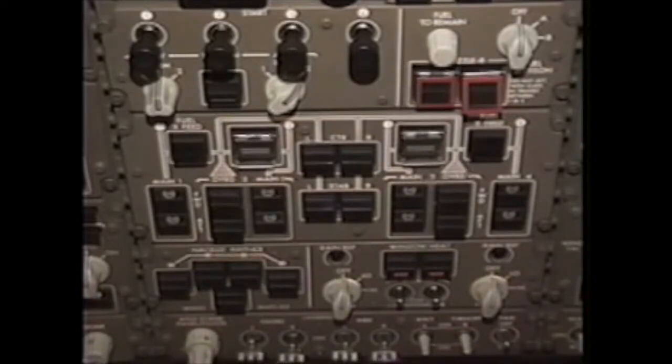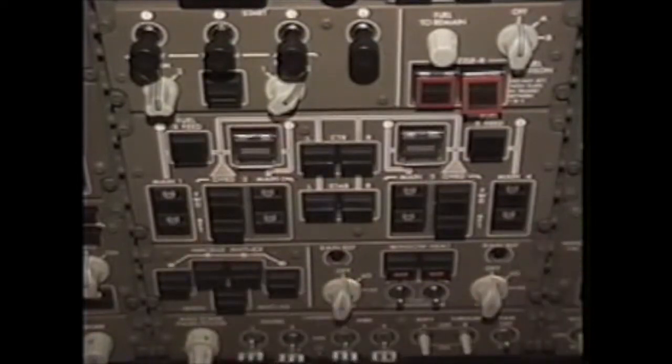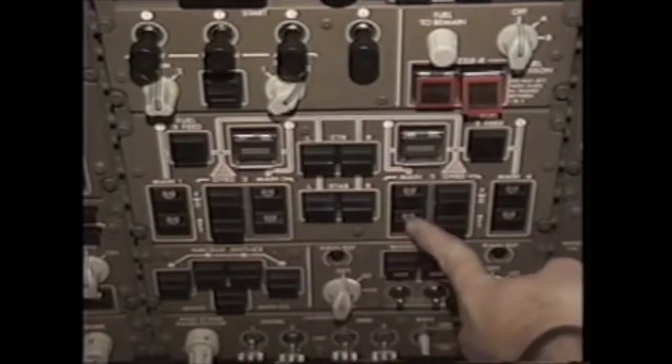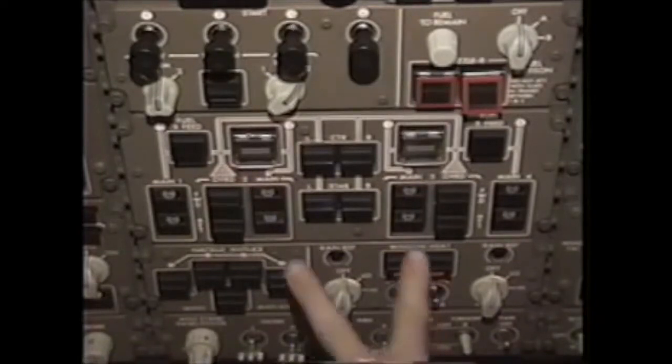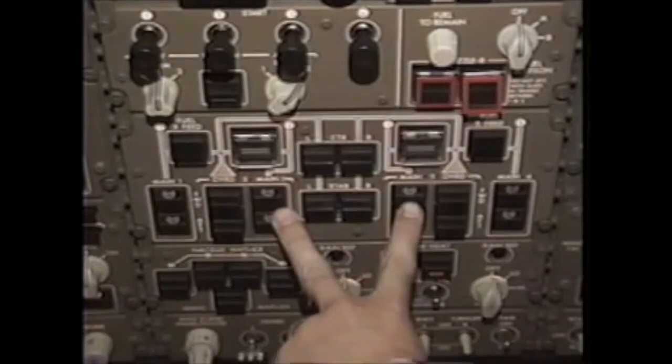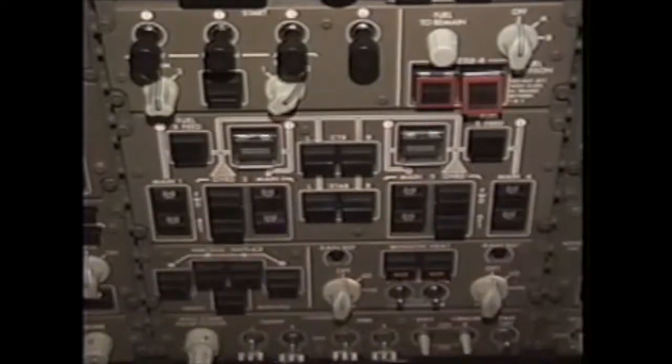Limitations has a minimum desired landing fuel value of 11,100 pounds. Fuel imbalance limits: the limit between main tanks 1 and 4 is 3,000 pounds. The limit between tanks 2 and 3 is 6,000 pounds. Whenever in tank to engine configuration, the total of main tanks 2 and 3 must be within 6,000 pounds of the total of main tanks 1 and 4. This limitation only applies when burning tank to engine.